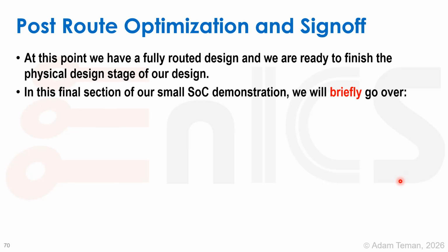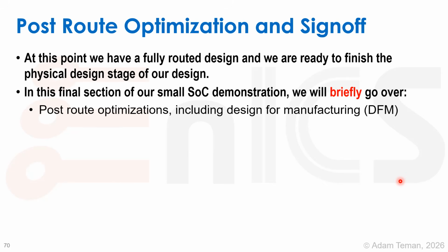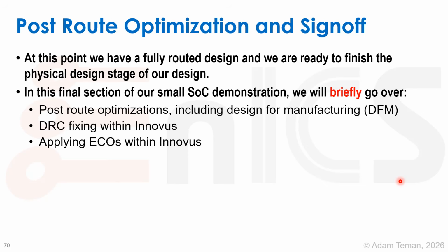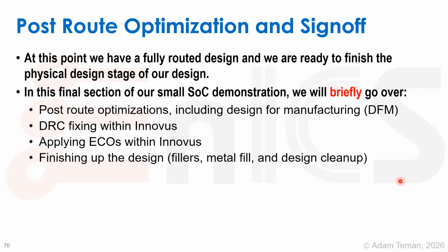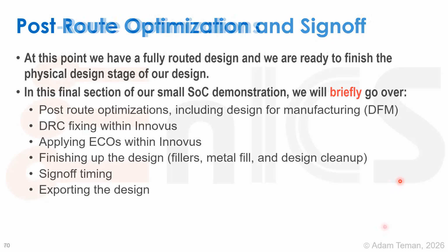In the final section of our small SoC demonstration, we'll briefly go over post-route optimizations, including design for manufacturing, better known as DFM, DRC fixing within Innovus, applying ECOs within Innovus, finishing up the design, including fillers, metal fill, design cleanup, sign-off timing, and exporting the design.